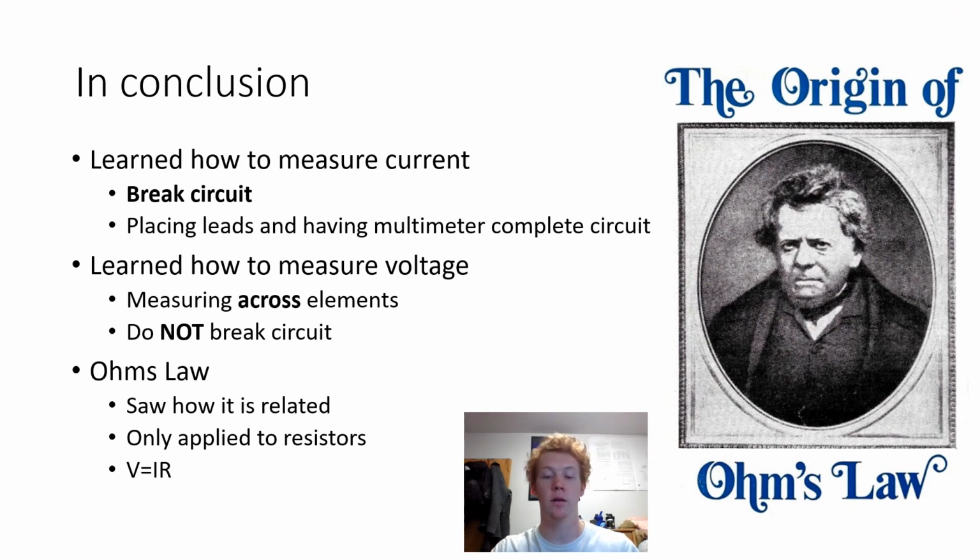In conclusion, you should have learned by watching this video how to measure current in a circuit. You also need to know that it is important to break the circuit when measuring current. You should know that the multimeter completes the circuit. You should have learned how to measure voltage, and you are measuring across elements, and you do not need to break the circuit. You should know what Ohm's law is and how to apply it.